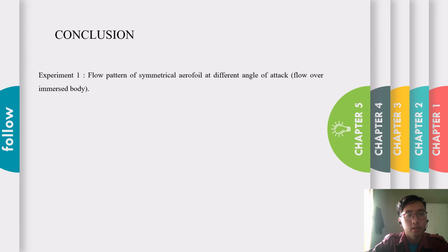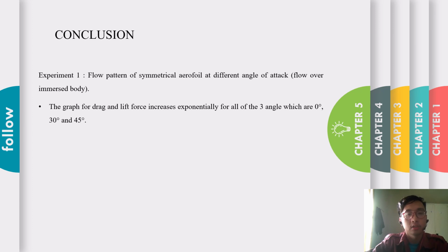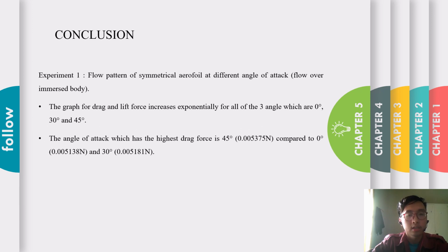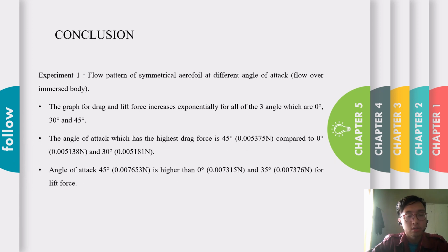For experiment 1, the flow pattern of symmetrical aerofoil at different angles of attack, the graph for drag and lift force increases exponentially for all three angles, which are 0 degrees, 30 degrees, and 45 degrees. The angle of attack with the highest drag force is 45 degrees, which is 0.005375 Newton, compared to the other two, 0 degrees and 30 degrees. The same trend also applies to the lift force, where the highest lift force is at 45 degrees, which is